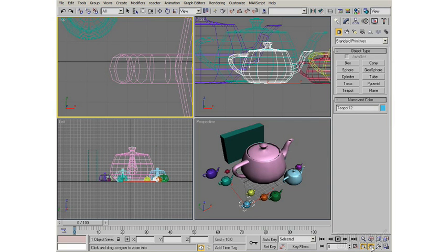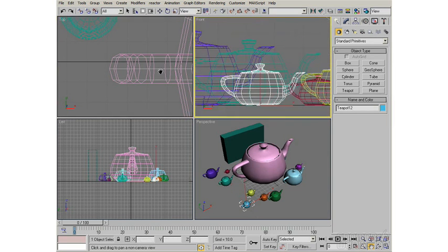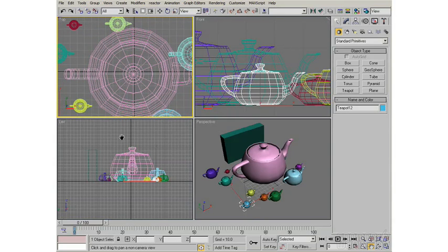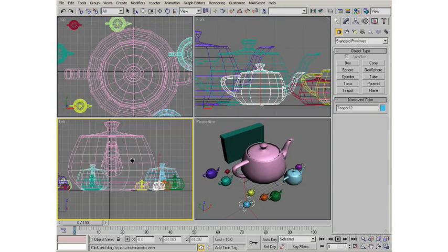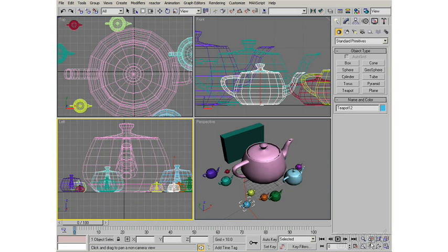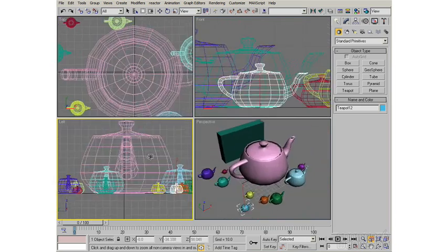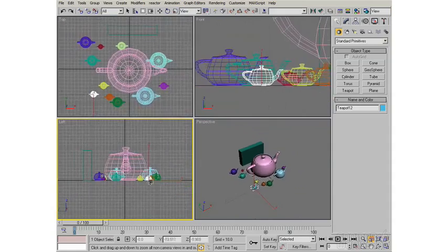Next to that, you have a hand. I almost never use this hand because it's the exact same hand as we had before, just by clicking the middle mouse button. So very rarely use this hand, if ever. Right above that, you have this button, which is Zoom All. What Zoom All does is similar to drag a box zoom, but it allows you to drag in any one of the views and it'll zoom all the views all at one time.